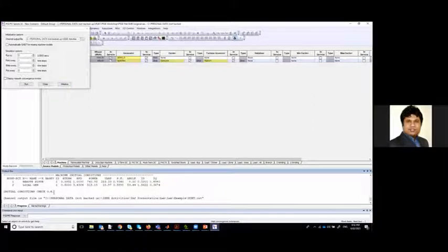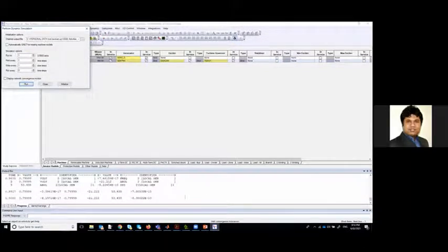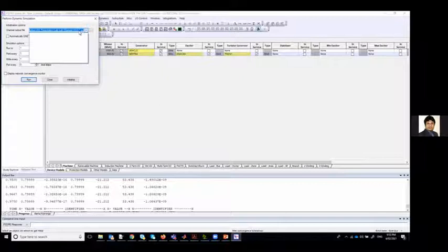If you see that the initial condition check is okay, that means your dynamic modeling is correct. If this initial condition check is not okay, that means there is a problem with your dynamic model. That means at every stage you can check whether whatever you have been doing is correct or incorrect. And let's now run the system up to 1 second. It's running. All those responses, the data, are given here. All this data is also being saved in the file ruet.out, this file.